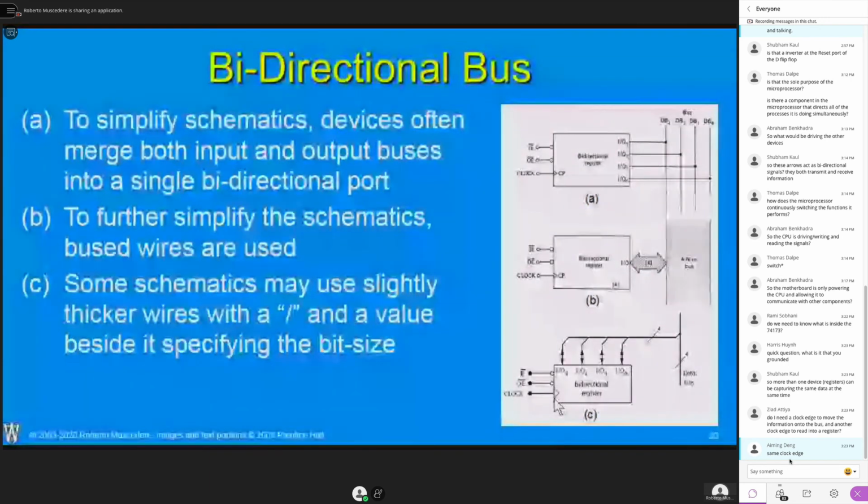We have some conventions typically. For example, what we'll see in this class is information always flows from left to right. That's one thing we'll often see, and we see that in a lot of the circuits in textbooks. Also, voltage levels are higher at the top than they are at the bottom. That's another thing we often see. But apart from that, schematics can look awful and still be functional, or they can look beautiful and still be functional. It's just a guideline for us. We don't really have a way of saying that what you see here is how it's actually built.